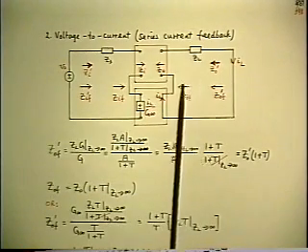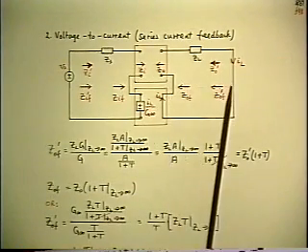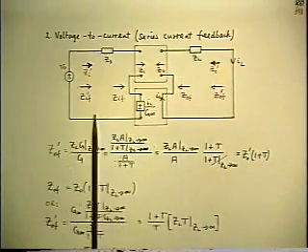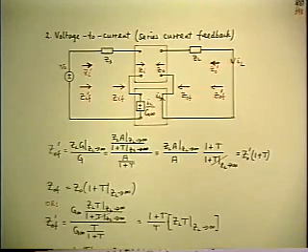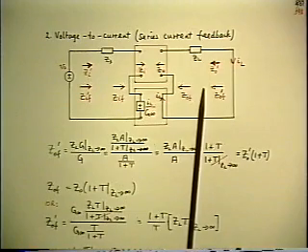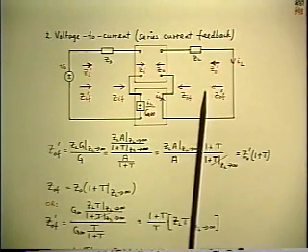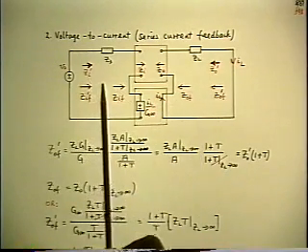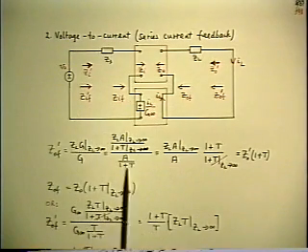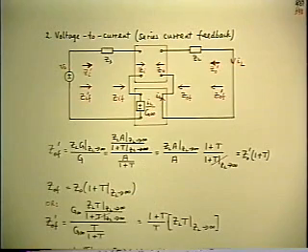Because notice that when we have this current sensing at the output, the configuration of the output circuit is identical to the configuration of the input circuit. So the new formula for the output impedance is exactly the same form as the theorem for input impedance, because the circuit configuration is the same.